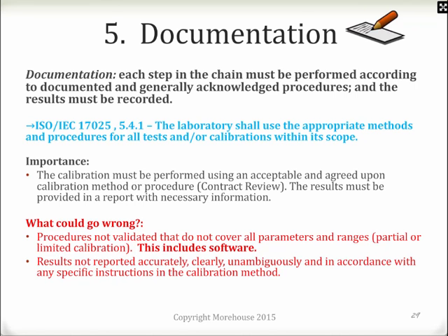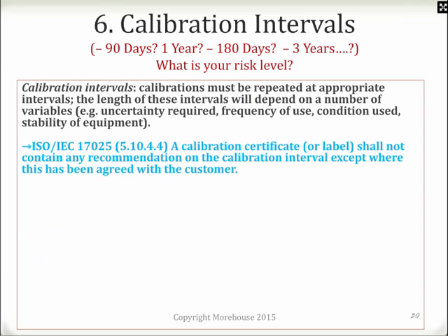So what else? Results not reported accurately, clearly, unambiguously, and in accordance with any specific instructions in the calibration method. Again, someone could give you the calibration report that says it's NIST traceable, where they did a shunt cal instead of actually applying a known force. This is pretty bad. It does happen.